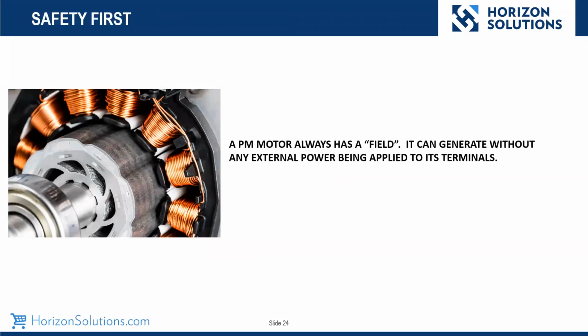And here I just want to caution everybody about permanent magnet motors. Remember, the rotor has the permanent magnets on it, and if the shaft is rotating at all, even if it's locked and tagged out at the drive, for example, there will be voltage present at the leads, and it's a safety issue. So please be careful out there. Next slide.